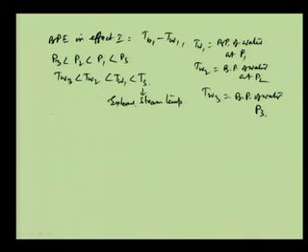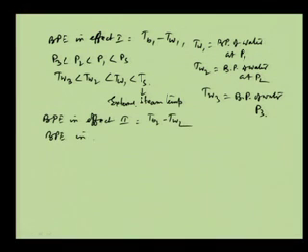And this is the boiling point elevation. So, boiling point elevation in effect 1 is this, BPE in effect 2 will be equal to Tb2 minus Tw2, and BPE in effect 3 will be equal to Tb3 minus Tw3.